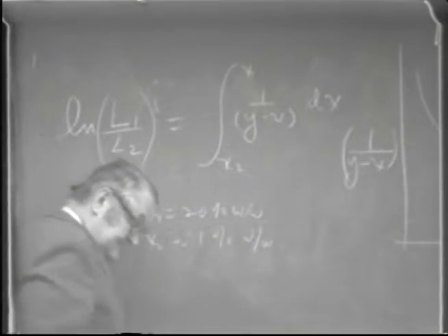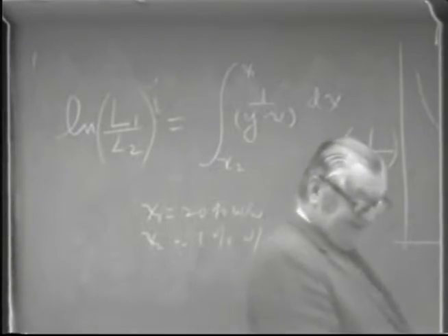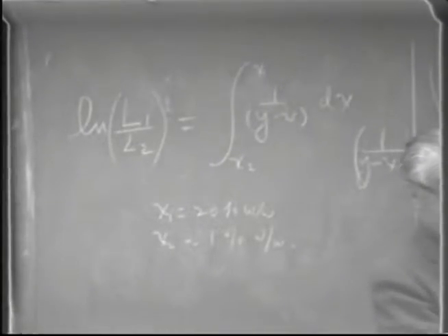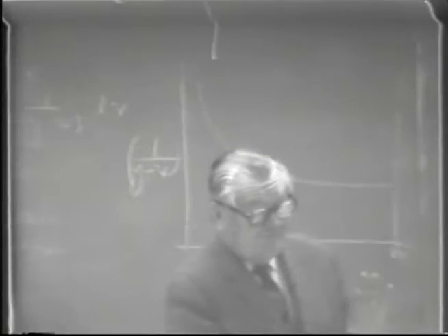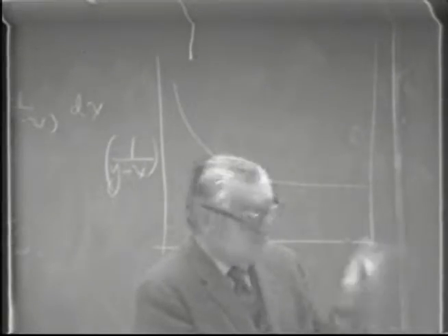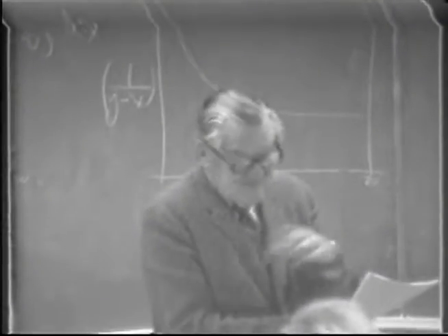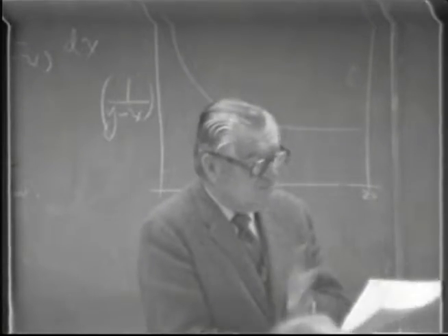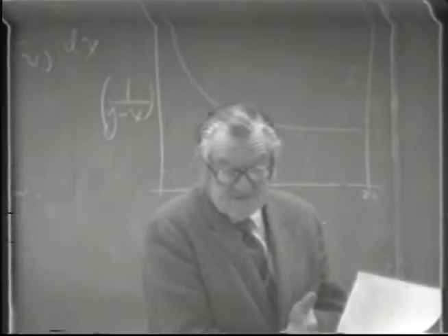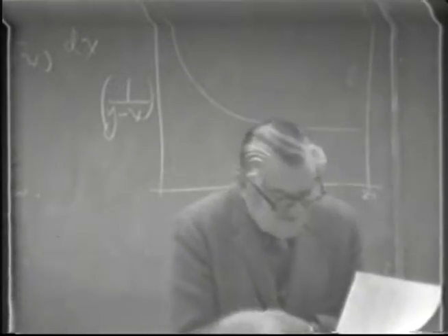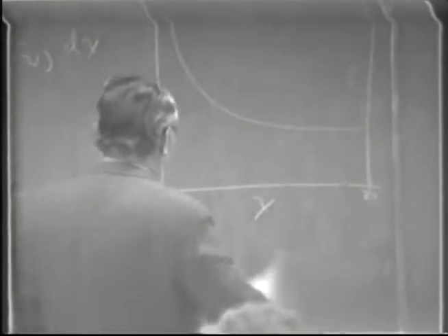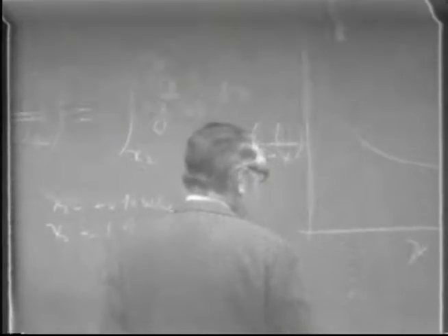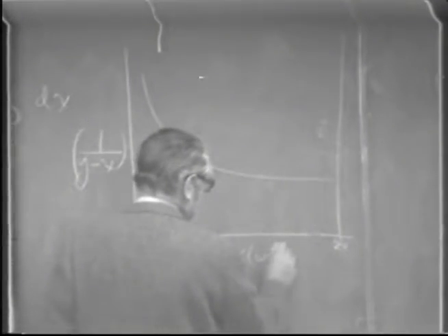by weight. And I remind you once more that since this problem does not require any assumptions of equal molal heats of vaporization or equal molal overflow, you can work on a weight percent basis just as well as you can on a mole percent basis. And so that was the basis by which the problem was stated. This is weight percent.